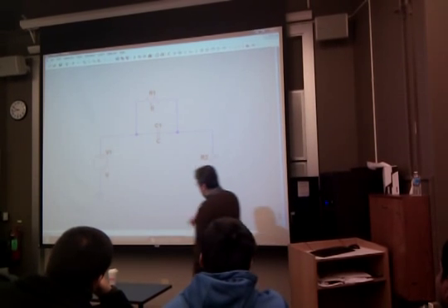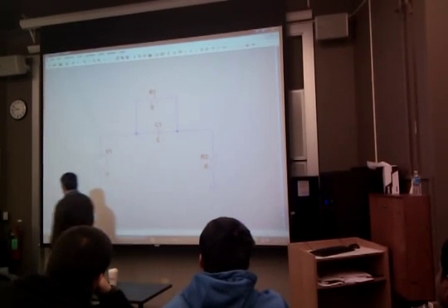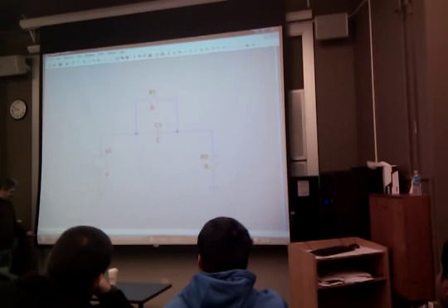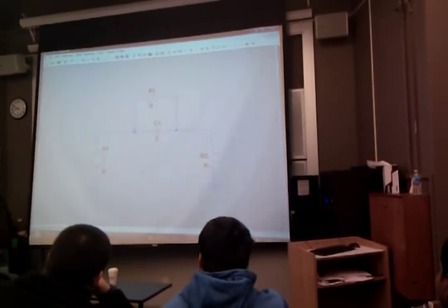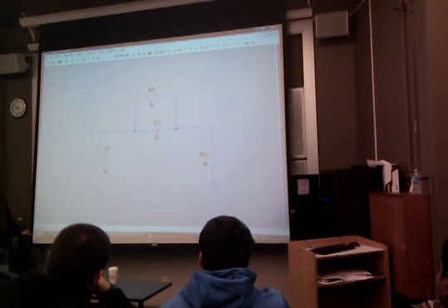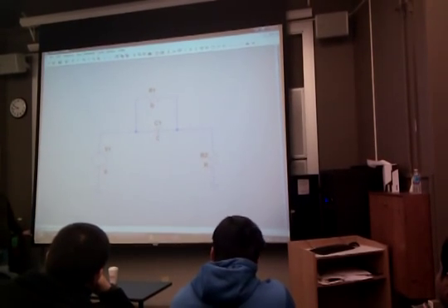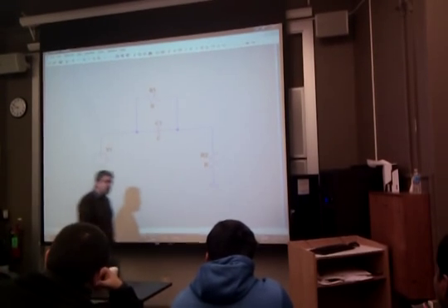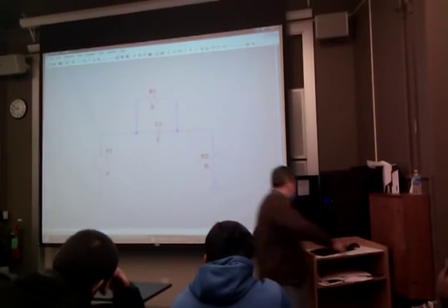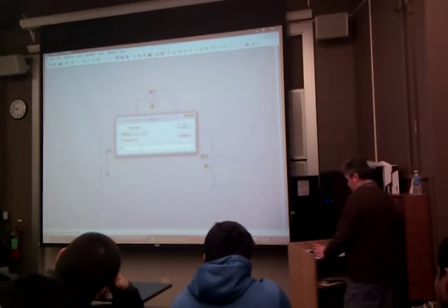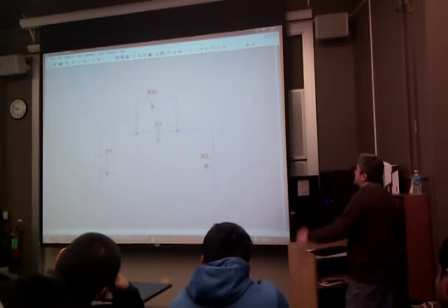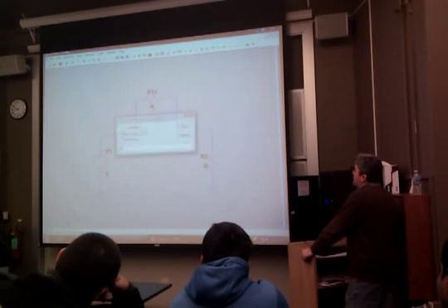And if you look at the lower corner here, it will usually tell you kind of what to do, right? It says right click to edit R, the value of R1. So R is the value, R1 is the designator. You can also change the designator too, right? But you don't put a number there. Like I can call this R1A if I want to. It doesn't really matter. I'll go up here and put in component values.